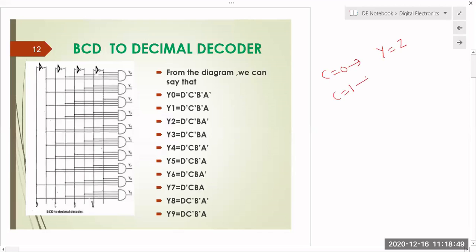Whenever it is active high, the output is exactly similar to the input. Okay. So whenever this C value is 0, this is your active low tri-state buffer. Whenever this C value is 1, this is your active high tri-state buffer. When it is active high, the same input that is there comes at the output; that is nothing but it acts like a normal buffer. Whenever it is active low, we cannot determine the output.